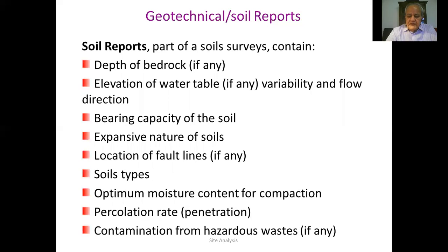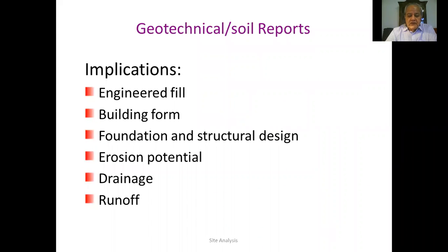So when we get the soil report from the soil mechanics, we get information about the depth of bedrock, if there is bedrock, the water table level, the bearing capacity of the soil, so that we understand which parts of the site are more appropriate, the expansive nature of the soils, which is very critical and dangerous, the location of any fault lines, soil types underground, the optimum moisture content for compaction if we are going to replace the soil, percolation rate, penetration rate of the soil, and if there is any contamination with hazardous material.